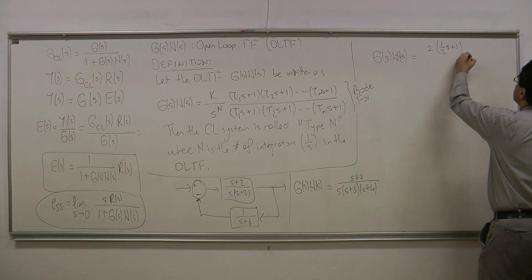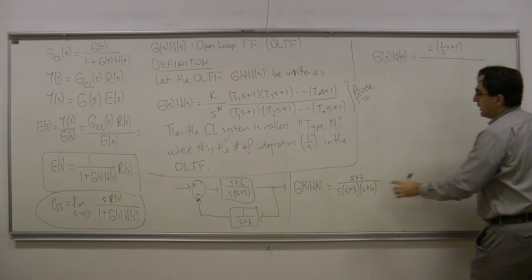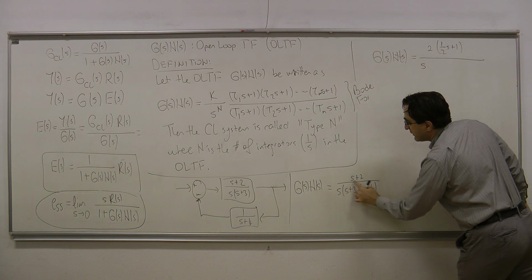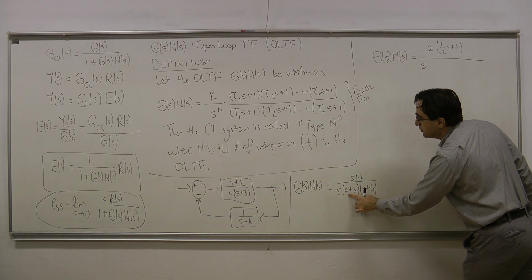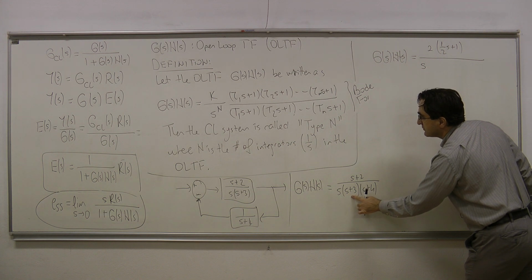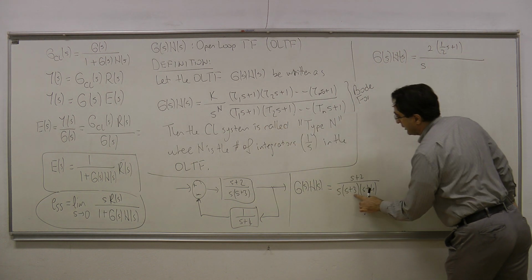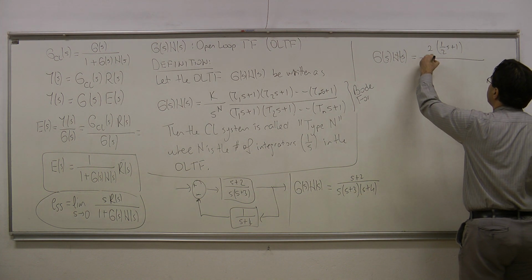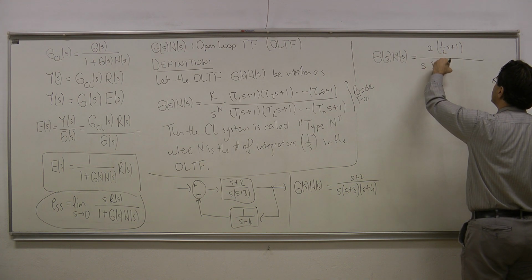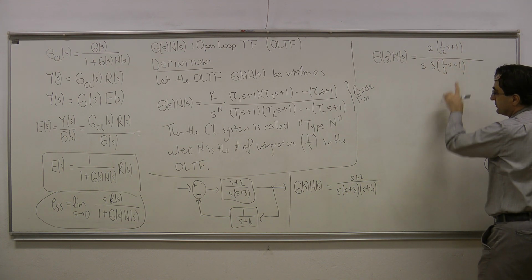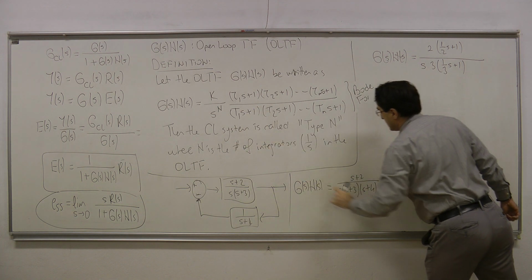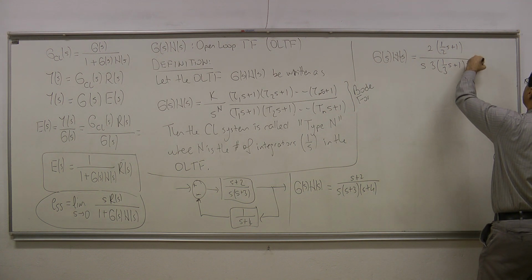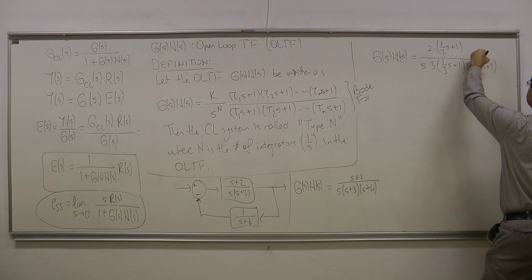All right? Divided by, I will leave this s term where it is, s, and I will take 3 parentheses here because I want to put this term in the parentheses also into its Bode form. I want to make the constant here equal to 1. So I will take 3 parentheses here. I have 1 over 3 s plus 1. Now this is exactly in this form. And I will take 4 parentheses in the last term here, for 1 over 4s plus 1. Okay?